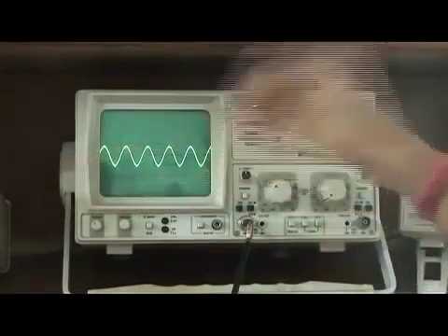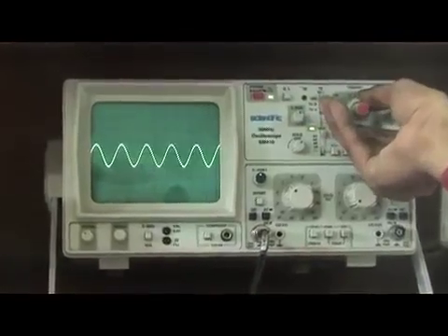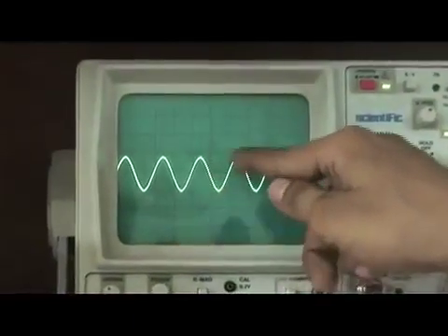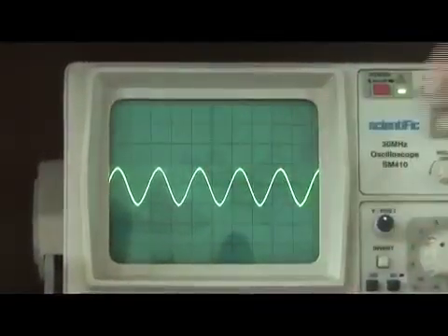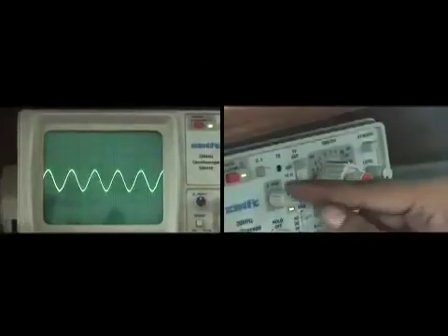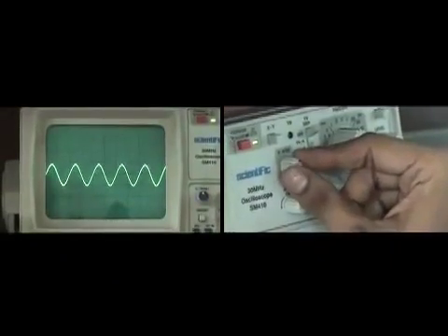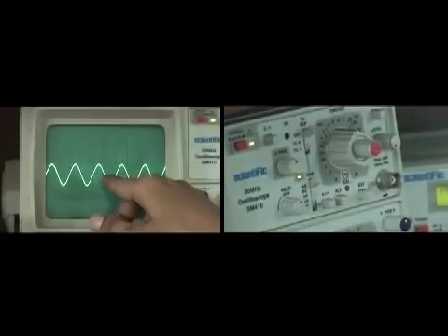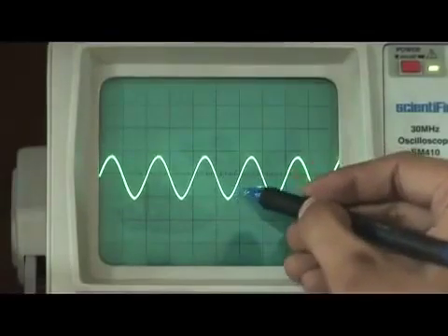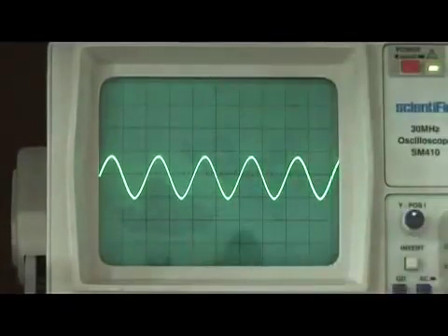And what about the x-axis? The x-axis can be changed using this. What lies in the x-axis? In the x-axis there is time. Time of what? Time of how many blocks one cycle of the signal takes to complete its rotation. Using this X position I can move in the X direction. I am setting it in a proper place where I can take a reference point and say that this is going to be 1. From here it is going this way, and till here it completes one cycle. So from here I can easily count the number of blocks.